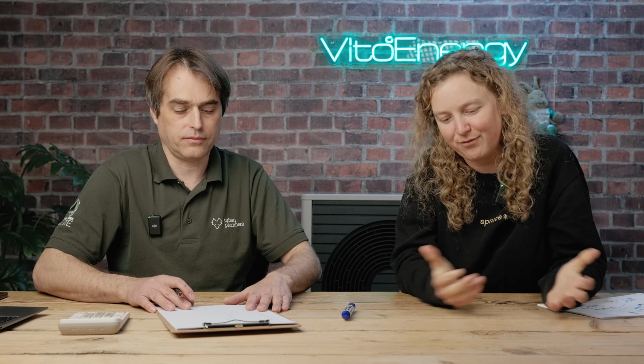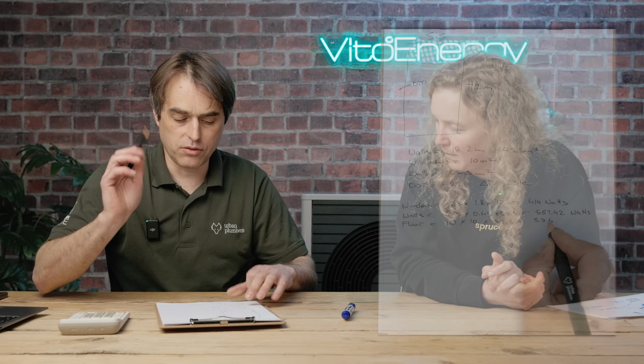So the very last thing left here is the floor. We don't have air on the other side of the floor. We must have a different DT. How do we know what DT we have, and how do we know what the U value of the floor is? Yeah, so with floor heat loss, there's actually 2 cases. If it's a suspended floor, then we do have air on the other side. We would use the design outdoor temperature. If it's a solid floor, then we would use the average temperature in the area, which is typically the ground temperature. It's probably around 11 for this location. So I'll use 11 here.